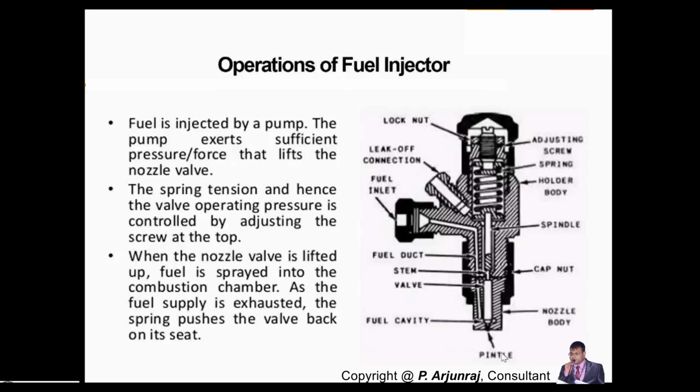A multi-hole with pintle type is also good, but with a multi-hole alone you need to control it, otherwise the quantity of fuel injected will be higher. To avoid that, you have the computer ECU-controlled operation, which helps inject the fuel in the right quantity and also helps atomization. But the pressure needs to be higher even in the case of multi-hole.